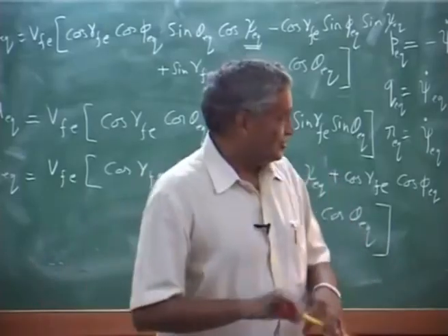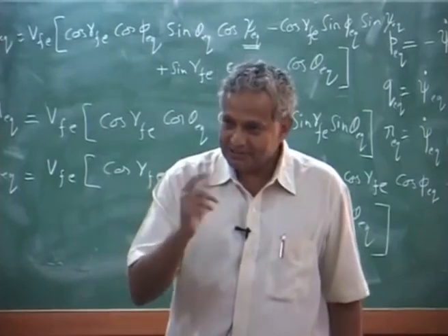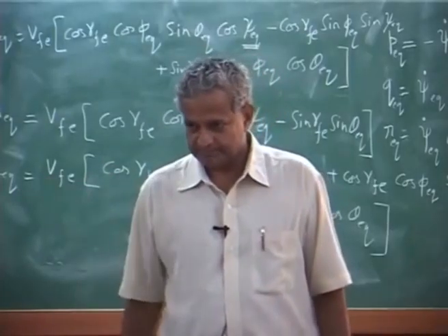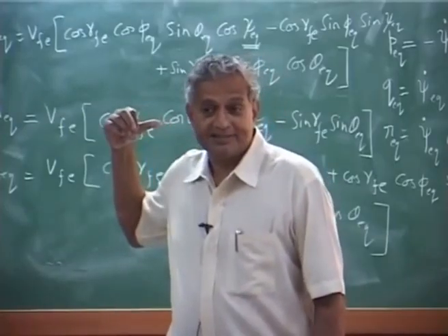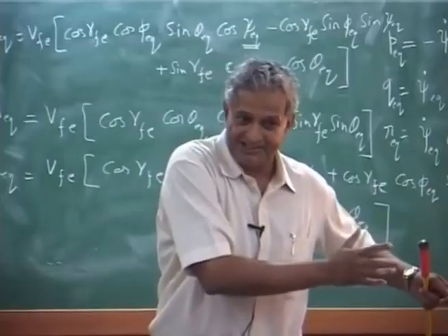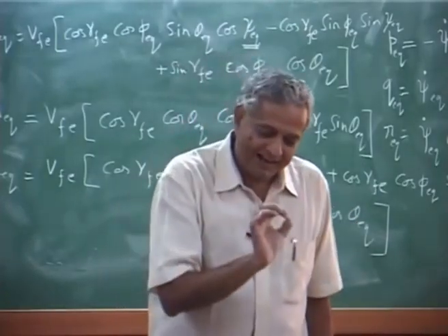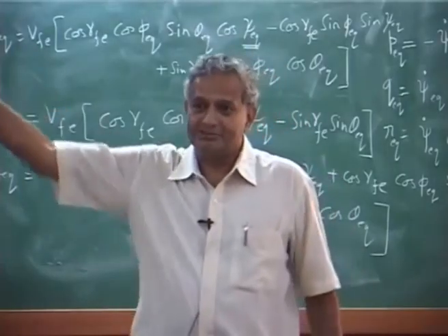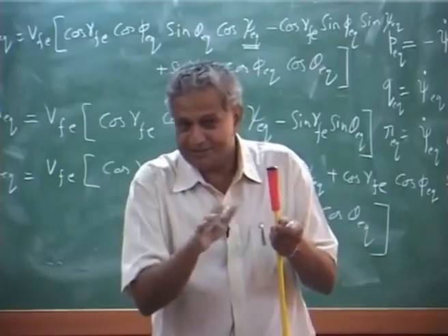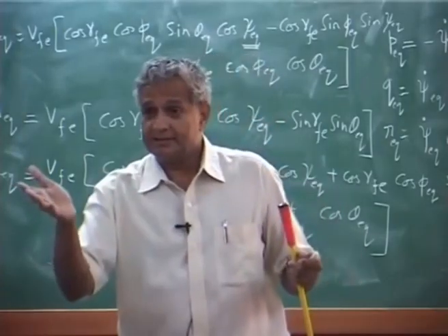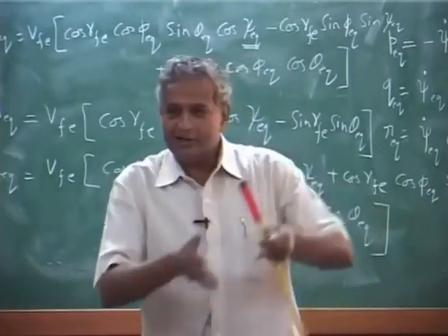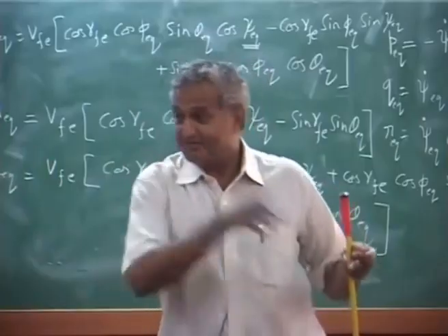Now, we want to do more complicated motion. Ultimately, the industry requires to know: if I give a control input, how will my vehicle perform? For that you can solve the linearized delta u, delta v, delta w equation, that is the perturbation only. Okay. But that will give you only what is happening at the instant, it will not tell you over a long time, because however you would have done the equilibrium about a hovering condition and a perturbation about the hovering condition, but you go to forward flight at some other speed, then you will have an equilibrium and a perturbation for that. Like that you will have equilibrium, perturbation, equilibrium, perturbation. You cannot say this perturbation will lead to that perturbation.